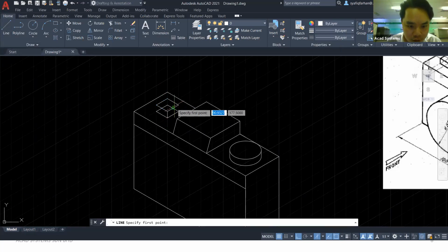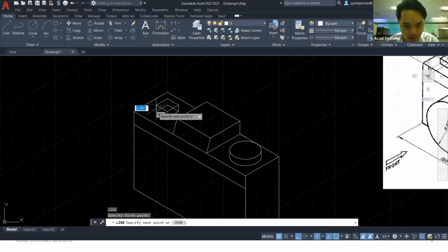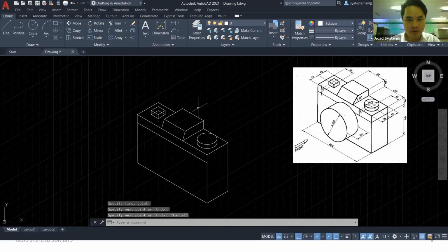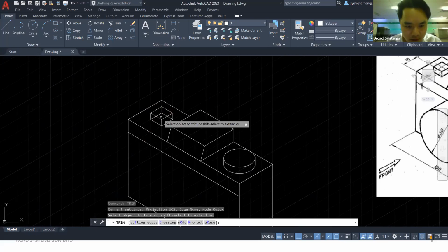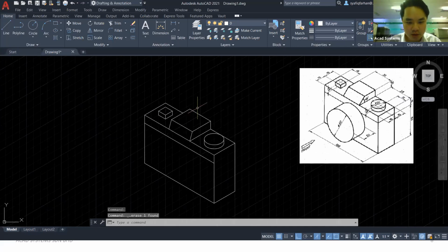And you add 2 more lines, and your button will be done. As I said just now, because we look at this 3D view, we have to keep this view, so we have to eliminate the lines that should not be seen. So we can delete this too. Yep, here we go. This one is for the shooting button, and the adjusting button has been done.